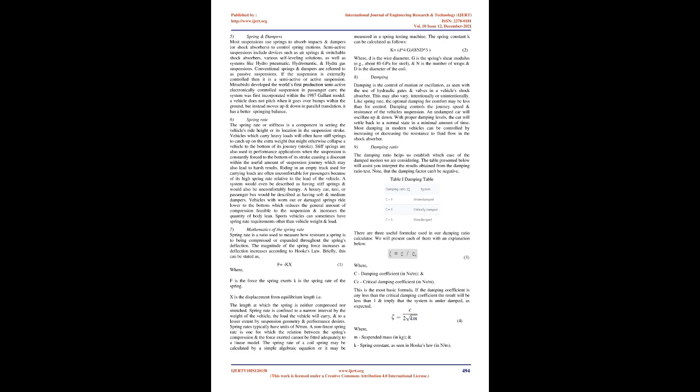B. Basic considerations. 1. Vertical loading. In vertical loading, the road wheel comes across a bump on the road. It's subjected to normal forces, tensile or compressive, depending on the load irregularity, which are absorbed by the elastic compression, shear, bending, and twisting properties of the spring. To minimize the pitching effect of the car, the front suspension should have less spring action than the rear suspension.